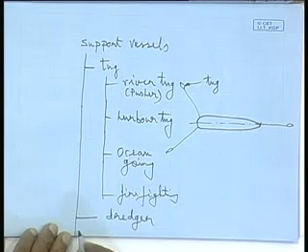Because of various other factors, siltation of rivers takes place, siltation of canals takes place, right? Because of this siltation, the draft availability or the navigability of the rivers or canals becomes poor. Means if you do not have the required draft, a vessel cannot move. So you have to clean that silt. Physically you have to take the silt up and throw it elsewhere. That is done by vessels called dredgers, which dredge. The dredging operation is basically digging up the silt and removing it. So another support vessel is the so called dredger.